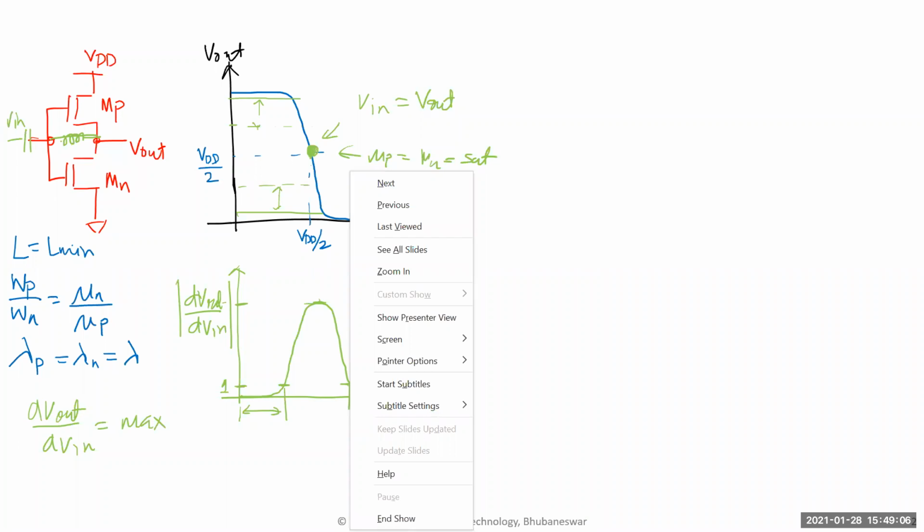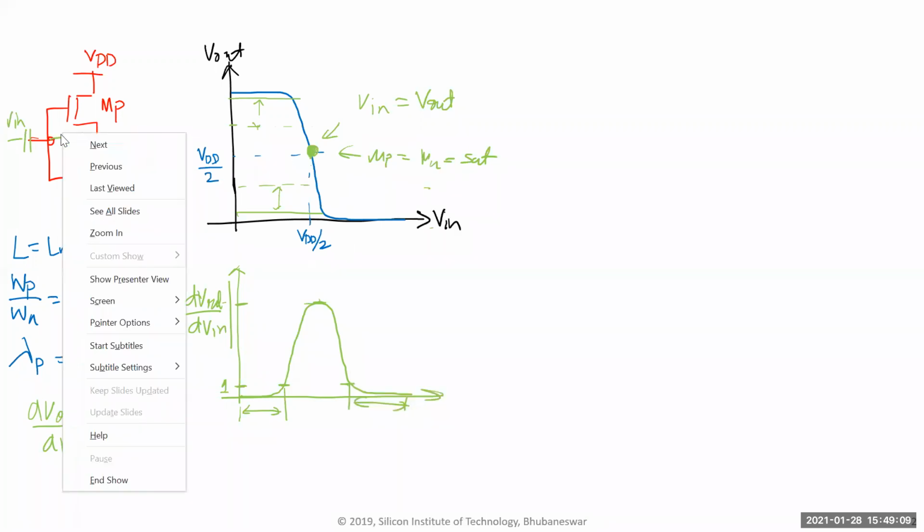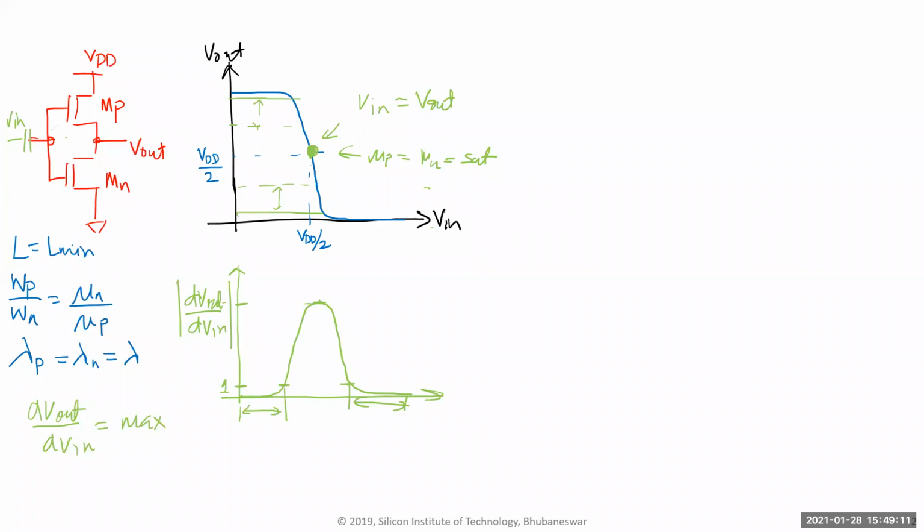What we do is, instead of putting an inductor, we just put a huge resistor here. Okay, so we just put a big value resistor. So there will be a small current at DC just biasing this. But if my amplifier is such that there's a large amount of current flowing through it, then it is okay. So as long as the resistor is large enough, it is okay. And doing large resistors in IC design is not an issue. It's fairly easy to do, as long as you're not expecting accurate values. And we don't require accurate values here. We just want something large. Okay, so that's your amplifier, right?